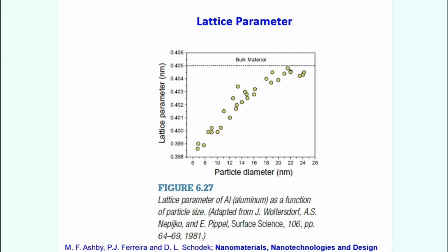The effect is so strong that even at room temperature nanoparticles can sinter, like gold, platinum, and silver, which have been found to sinter. And then finally, I discussed the lattice parameter effect, or the effect of size on the lattice parameter.